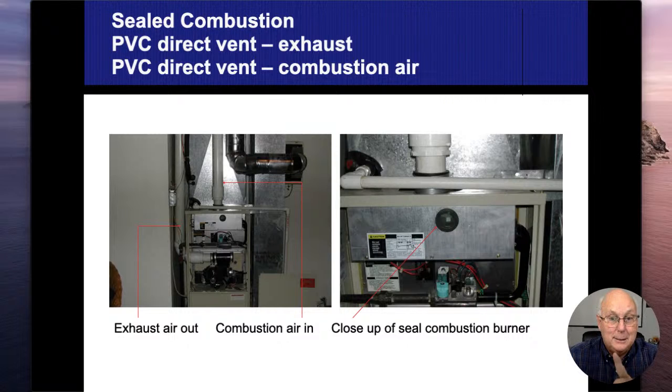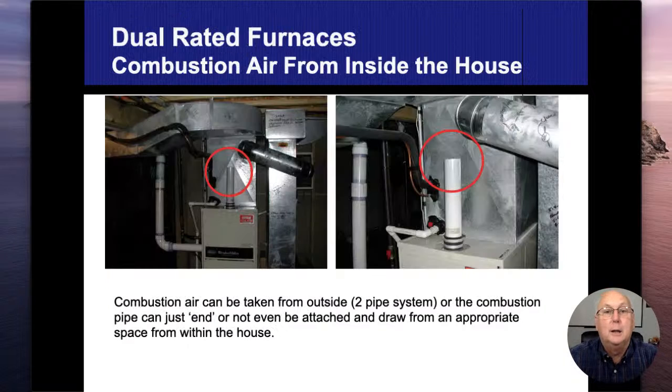Now these plastic or the high efficiency units, that sizing of the vent connectors, they can get bigger or smaller. So that sizing to the appliance is only for the mid efficiency furnaces, not necessarily for these. But we still want to make sure, no, there's not much we can do because they are going to condensate. Liquid is going to come back. They are going to collect it and they are going to drain it. That's what they're for. So I may have mentioned before about bringing combustion air from the inside. So this high efficiency furnace can operate this way if I'm in a wide open basement.